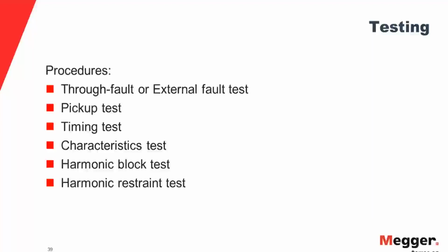for testing. On the element and scheme testing, it is entirely up to the utility or the governing body to determine whether they need to mask the other elements when you're testing a differential function, or whether they want to do a scheme test based on the settings of the system, which obviously requires a lot of knowledge or understanding of the scheme that is being implemented.